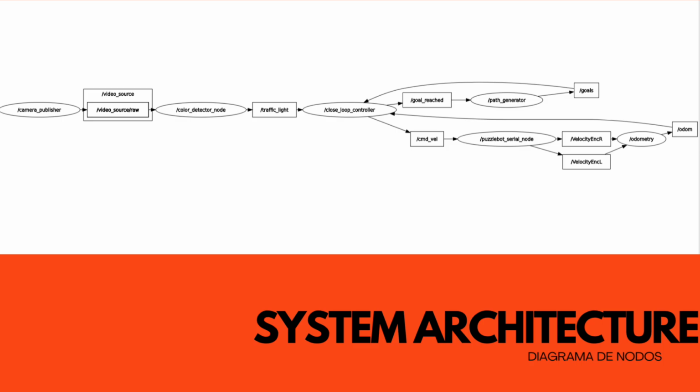The camera publishes raw images to the color detector. The color detector publishes the detected traffic light state. The odometry node estimates the robot pose using encoder data. The path generator publishes the desired waypoints, and the closed loop controller uses the odometry and the goal position to generate velocity commands for the robot.